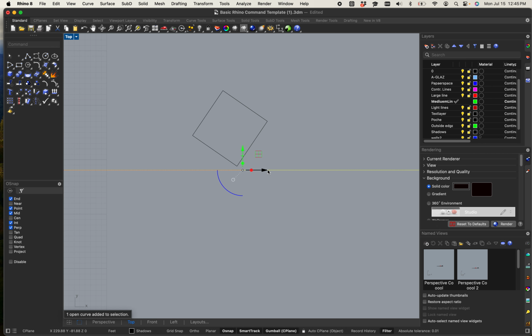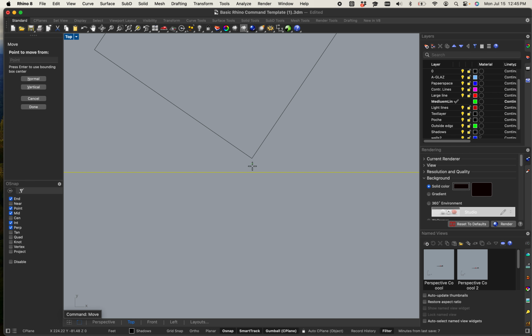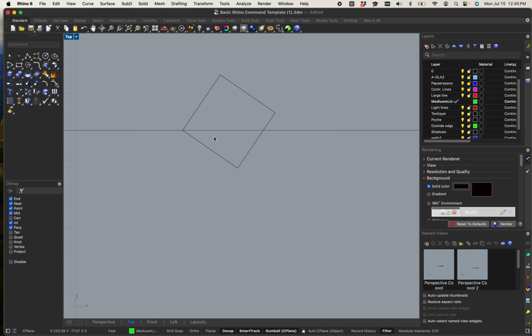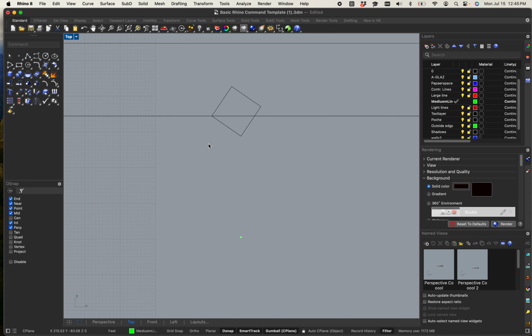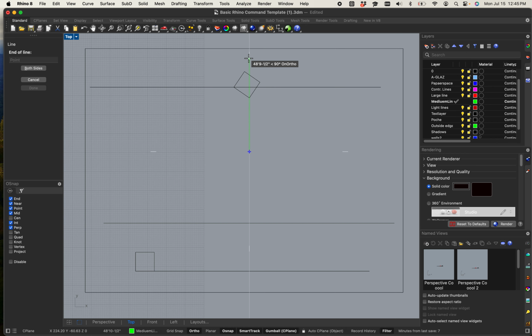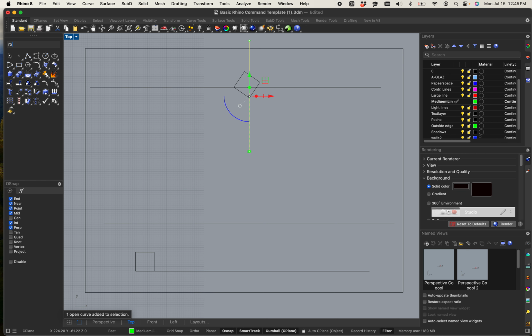Well, in my case, I want to move my stationary point or my perspective plane to something a little more realistic, say maybe this back plane right there. That way half of it is getting projected out and a larger half is getting pushed back. Next thing I want to do is set up to where I can get my vanishing points. So I'm just going to make some arbitrary lines and rotate them 45 degrees.